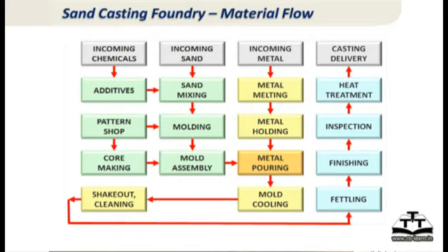The sand may be sent back for recycling and much of it can be reused. And on the other side, the castings, which still have the gates and feeders, are taken to the other side for fettling, where you essentially cut off the gates and feeders. Then a little bit of grinding and finishing, maybe some rough machining, maybe before or after inspection. Inspection itself is done in different ways, like X-rays, or it could be measurements, or dye penetrant, or ultrasound. And then some castings may be heat treated if necessary, and they may be painted before they are delivered. That's a typical flow chart in a foundry. Most foundries try to lay out so that the material movement is minimized, so in a compact area you can have high productivity.